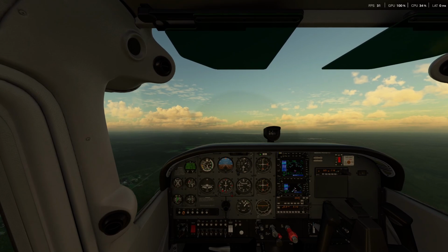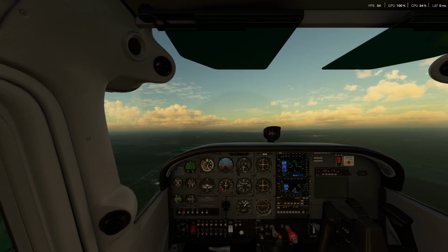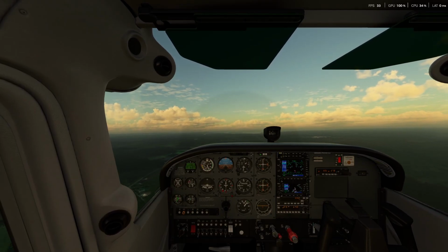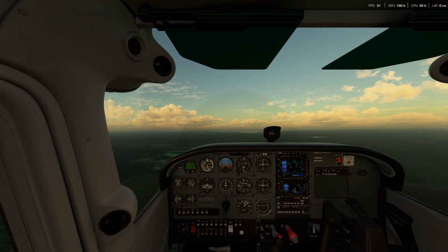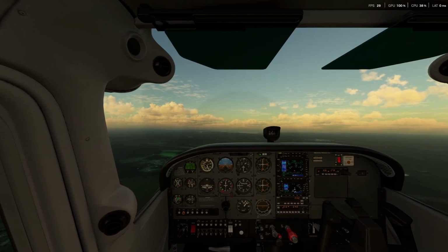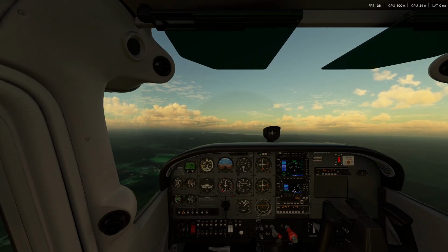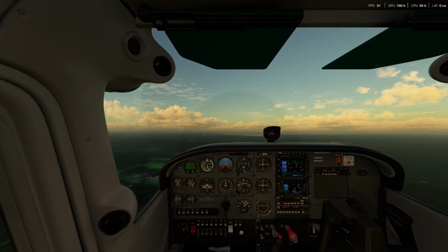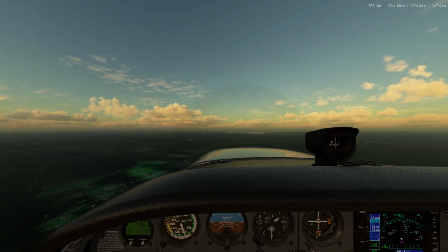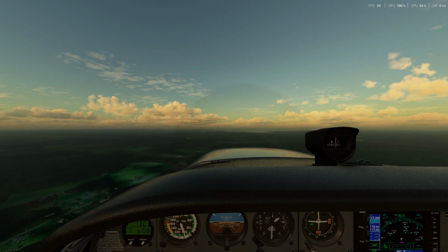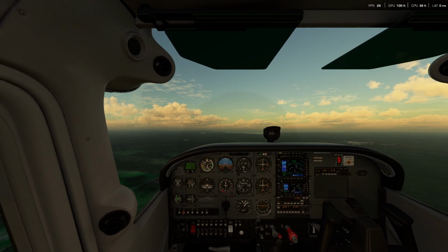So the mixture rich, pitch attitude is as required. Throttle set full. That was already complete. Now we're on time for level off setting. Trim, flaps are up, lights off. We're going to keep all the lights on. And then the next thing, engine cowlings. You want to check and make sure that there's no oil leaking from the engine, but anyways, engine cowling is good.